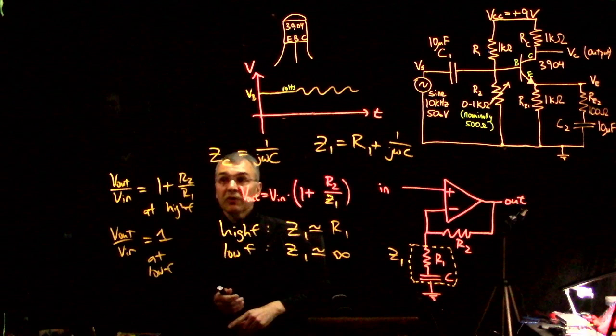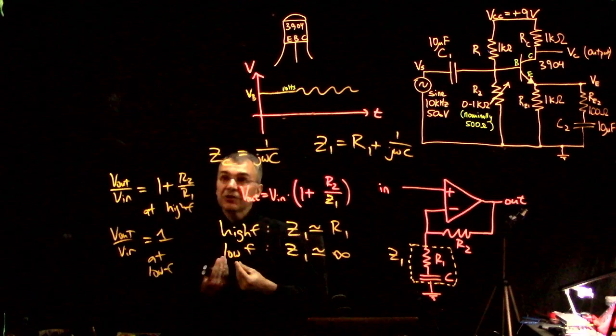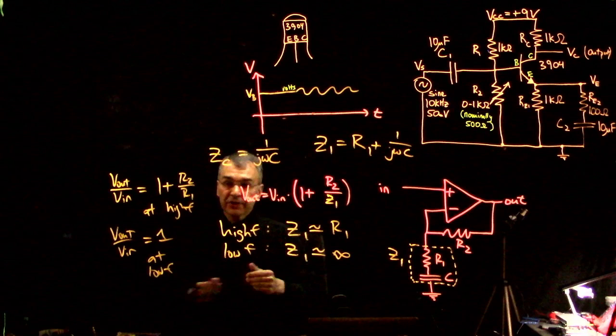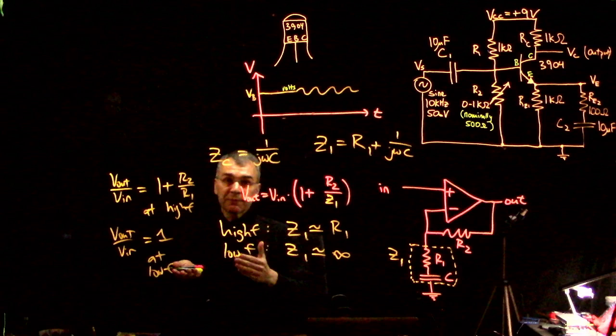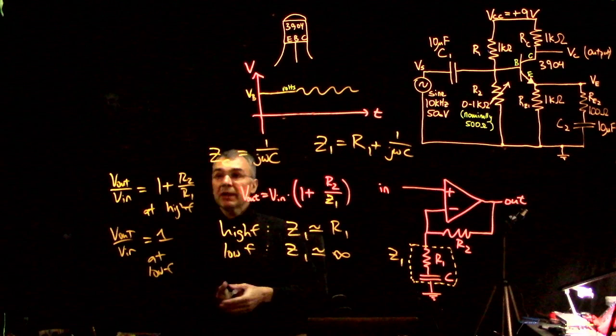And we made an amplifier that could amplify the microphone signal by a factor of about 100, and meanwhile it only multiplied by 1 the DC effects that were kind of annoying, like the op-amp imperfections.